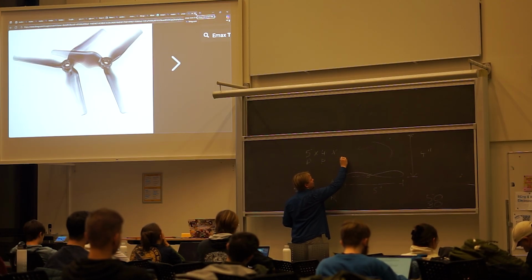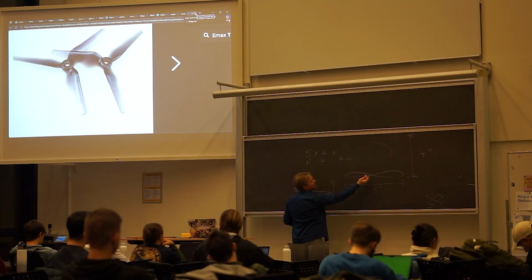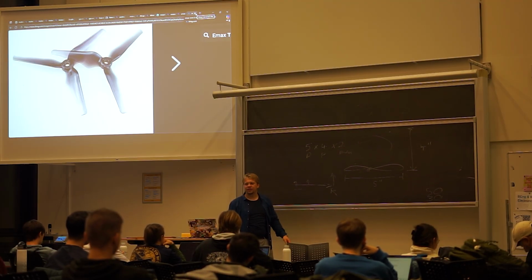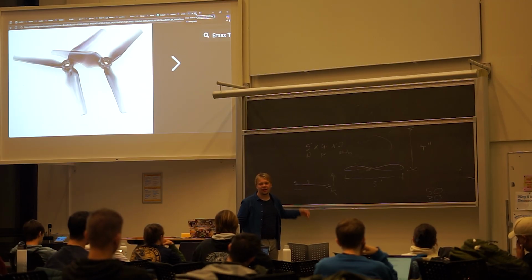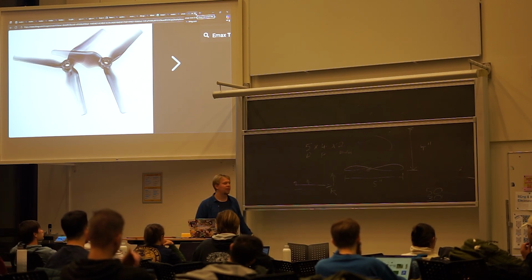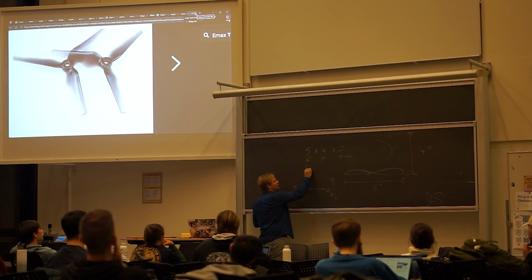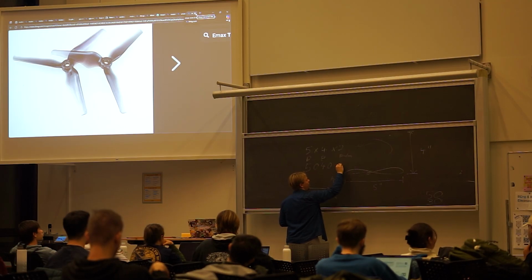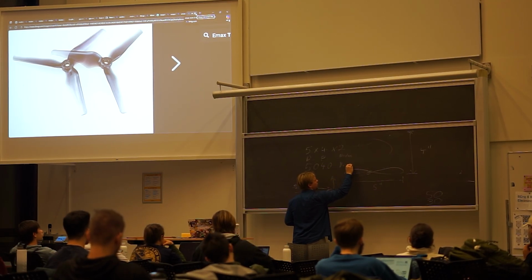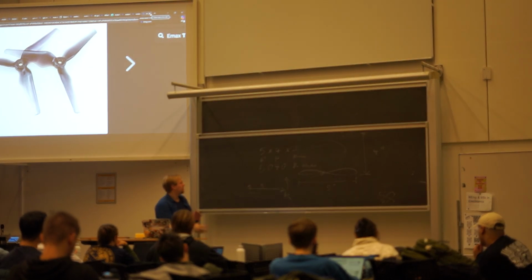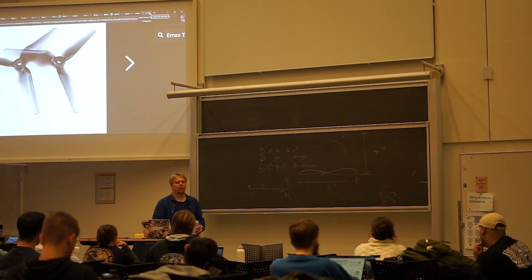Blades. This is a bi-blade, so that would be 2. So it would be 5x4x2. That's a 5x4x2 prop. It does describe something, but it doesn't describe the whole prop anyway. So that's kind of how it works. And then there's the second naming convention, which is this would be the 50-40 bi-blade. So it's either the 5x4x2 or the 50-40 bi-blade.